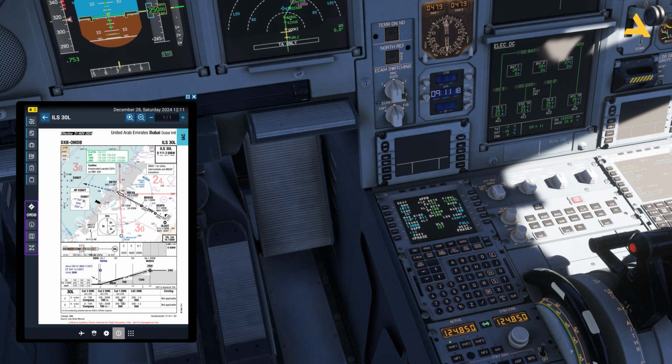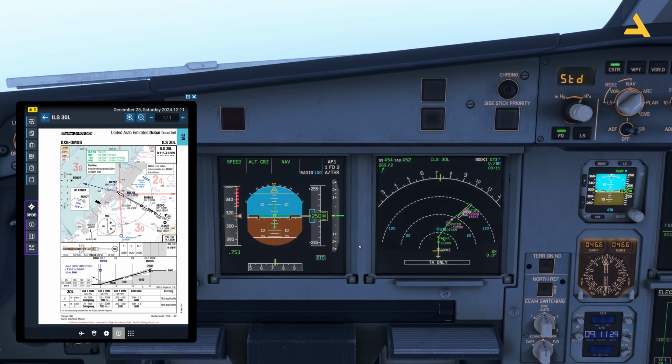But if you want to hear this callout at 260 feet above the runway, then you go with the baro, 260. But at one time, either you can have baro or the radio. That's it. Now you can see it started to appear over here.